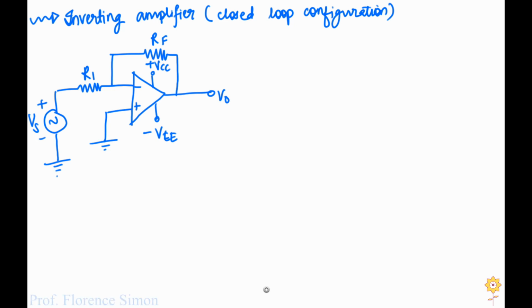In this video we will be learning Opamp as an inverting amplifier in closed loop configuration. So here I have drawn the diagram. We can see that these are the two input terminals. One is the inverting terminal denoted by a negative sign, and the non-inverting terminal is denoted by a positive sign. Let's call the non-inverting terminal V1 and the inverting terminal V2, and the difference in these two input voltages is VID. So VID is the difference in input voltages and the output voltage is VO.